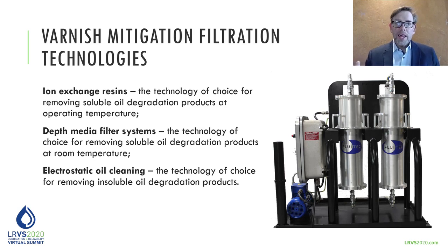Well, any of you that have spent some time either working in the energy industry or working for customers in the energy industry are familiar with the varnish mitigation technologies. These are prevalent in power generation, petrochemical, and air separation operations, and there are several different technologies available in the market. There are ion exchange resins, depth media filter systems, and electrostatic oil cleaning, and in the right applications, these technologies can do a really good job. They are not ideally set up for hydraulic applications in many cases.